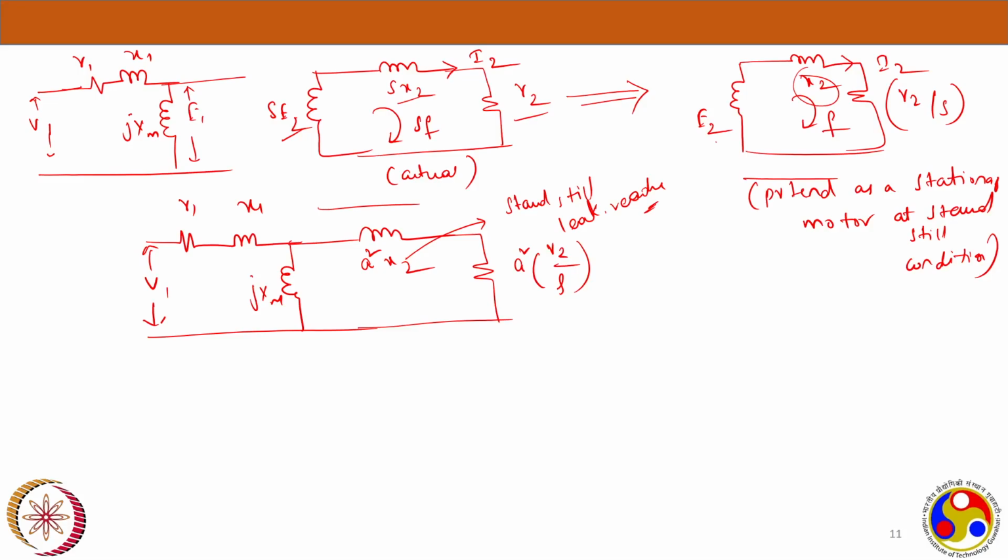The reason we are changing it is to bring a situation where the input frequency and the rotor side circuit frequency are the same, so that I can join these two by keeping the behavior of the machine the same. My stator should not find any difference between these two circuits now. That's why we discussed this, and how my particular stator is seeing the circuits.